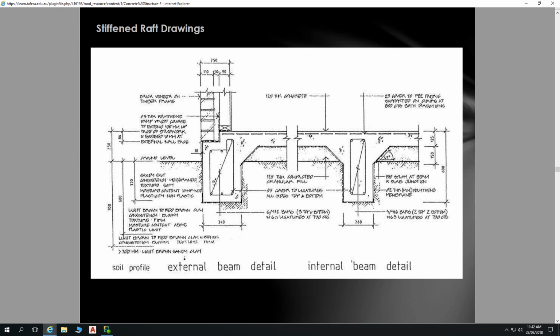Some details there. So just be aware this detail exists here in case you want to refer back to it. I think I've drawn this detail a few times already. We've got our top and bottom bars happening there. We've got our rebate for our brickwork. Our brickwork sits down lower than our structural timber. And for anybody who wants to describe brick veneer for their first assignment, for example, maybe that's a good thing to look at. It shows you your structural timber frame and then your veneer of brickwork and how that sits on your concrete raft slab, and how all of that sits above the ground.